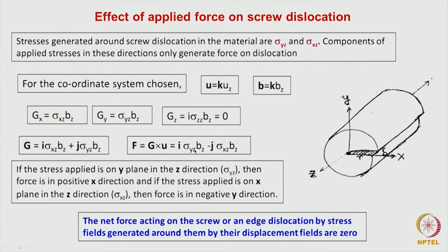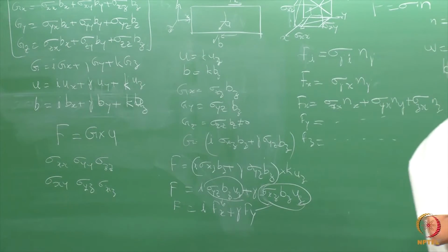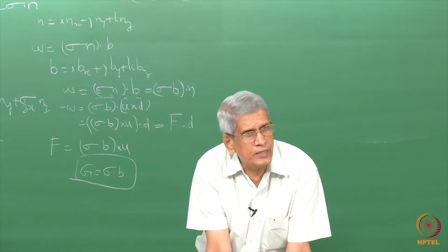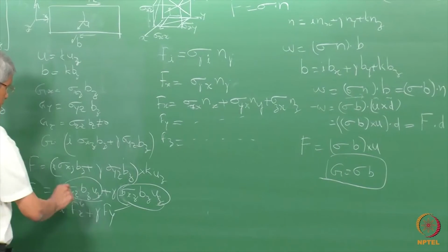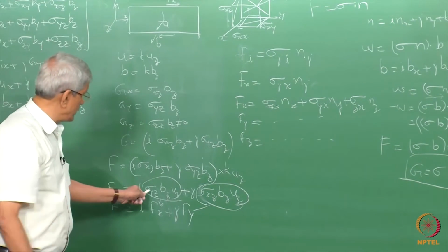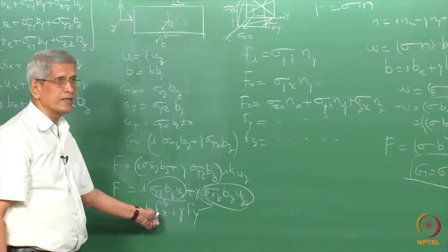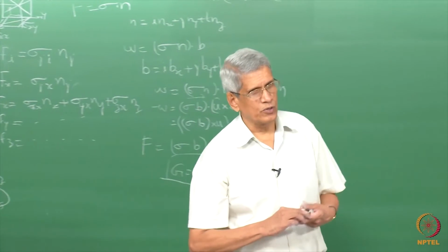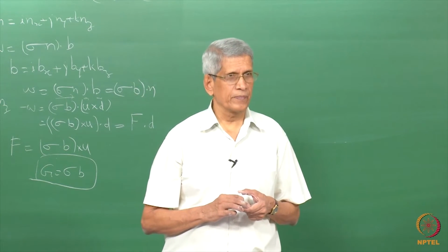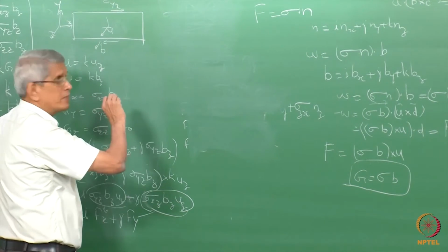At any particular point with respect to a dislocation, we are trying to find out what the external stress acting on it is going to be, correct? Suppose we apply yz. What it tells is that the force is going to act in Fx, that is, in the x direction, in a screw dislocation. This is equivalent to the case of the screw dislocation which we have considered.